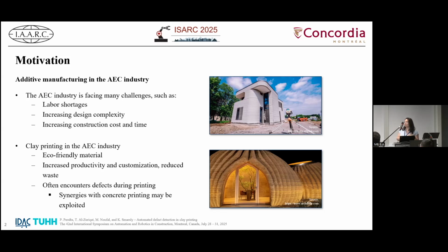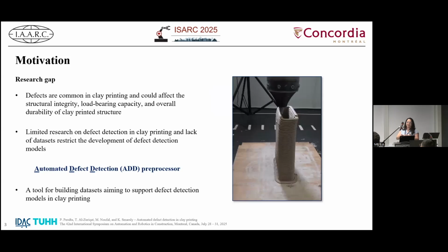So here we can explore some synergies with concrete printing, since we observe very similar defects, right? We have tearing, we have sagging, and we can also have cracking during shrinkage. So with this, we define the research gap: these defects usually affect the structural integrity, the load-bearing capacity, and the overall durability of the concrete printing structure.